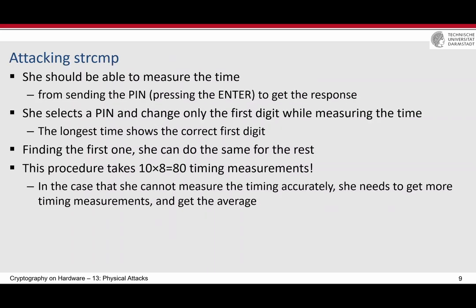And then how to attack this? The attack is easy: by measuring the time. The attacker needs a device to measure the time, based on, for example, nanoseconds, picoseconds, or microseconds, depending on the device and technology. Sometimes you measure or count exactly the clock cycles, but sometimes the clock cycle is not known, and then you need to measure the time exactly.